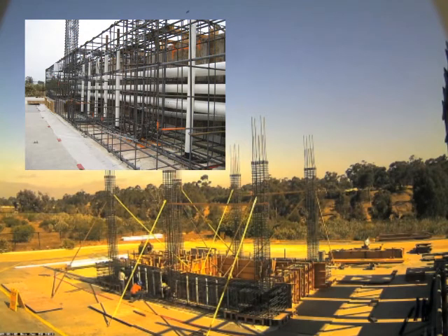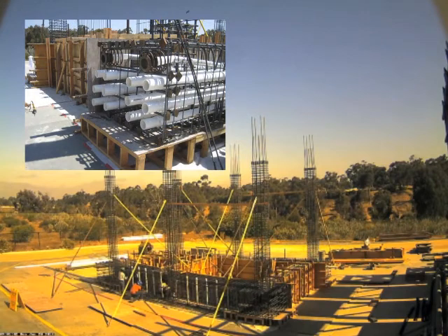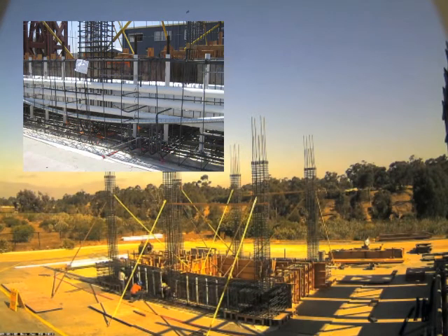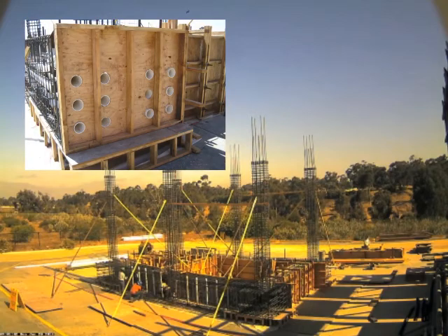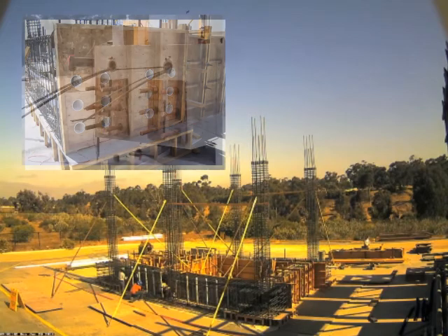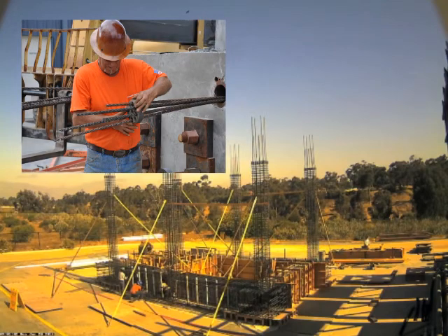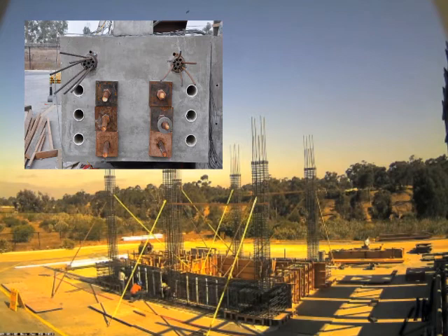Post-tensioning can be done in two forms, bonded or unbonded. In this project, both bonded and unbonded post-tensioning were used. High-strength rods and tendons were placed inside PVC ducts, which were cast within the foundation. The rods were left unbonded and tensioned after placement, while the tendons were bonded with the grout and then tensioned.